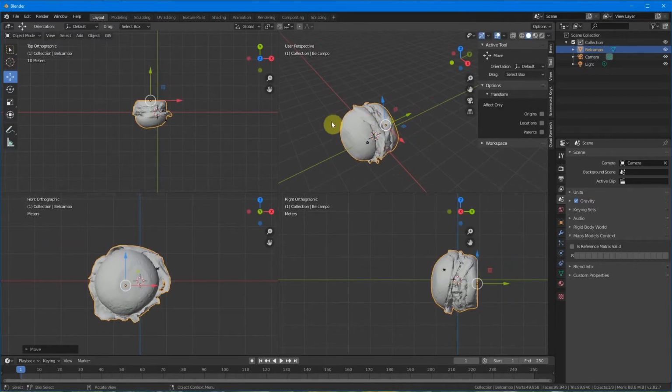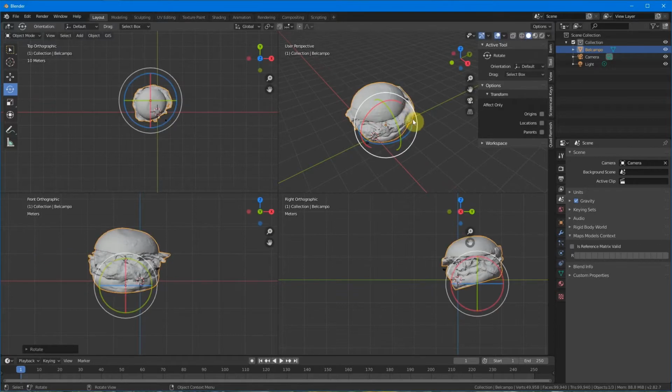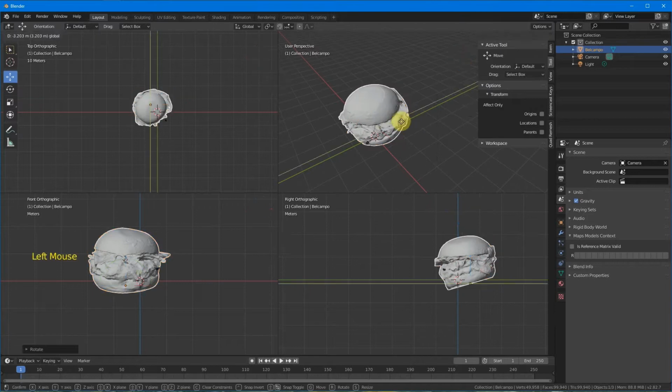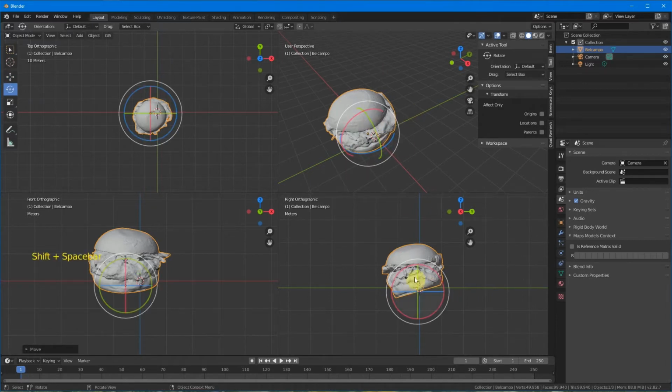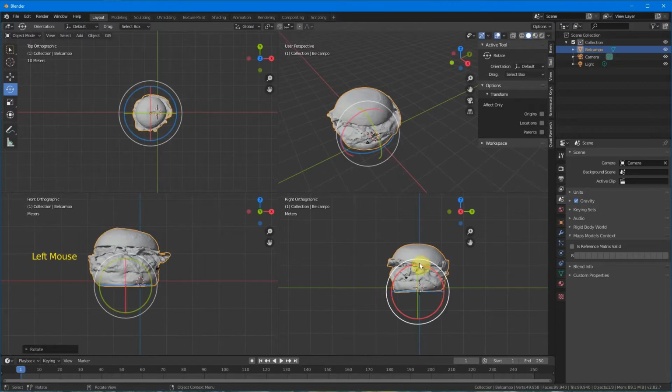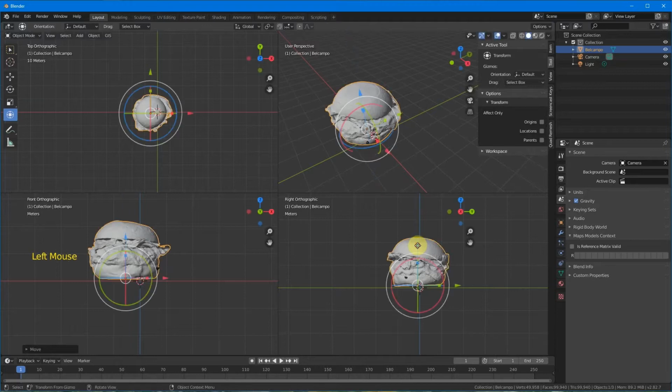And also we want to rotate this. There are shortcuts: you click on Shift Space, and then you can select which tool you want to use. So we can click on move, and then we can move it. From this X perspective, we can see it's a little bit tilted, so we still want to rotate it, and then we press R, and we can rotate it a little bit. And to move it, transform, move it up, and rotate it a little bit more, put it down.